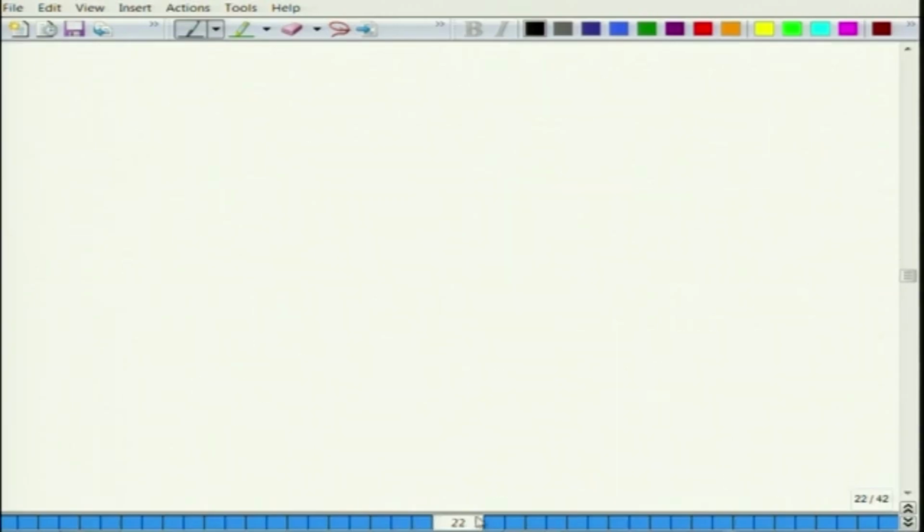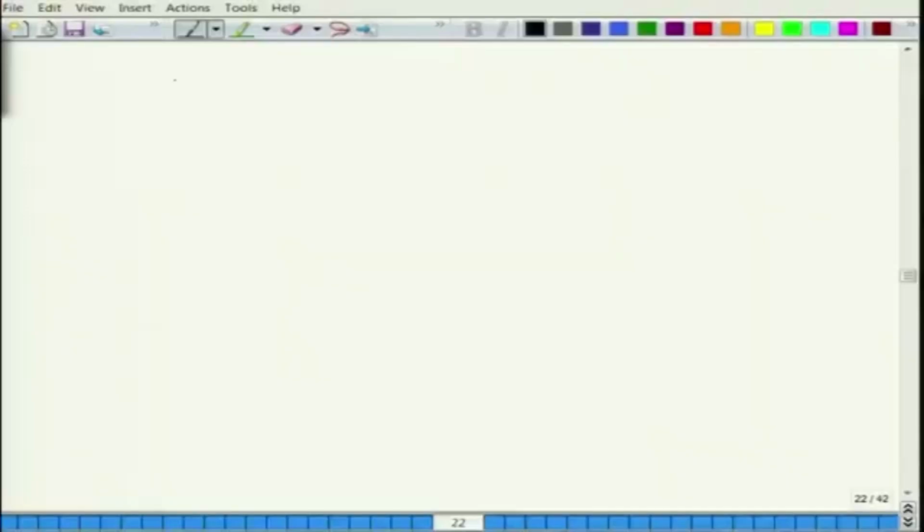Okay. So, here one thing we have to note, that we have assumed the heat transfer coefficients between the air stream and the plates are known, right. HFP or HFB, all these things are known, that we have assumed, but how to know that, right. So, a note on the heat transfer coefficients. Okay.